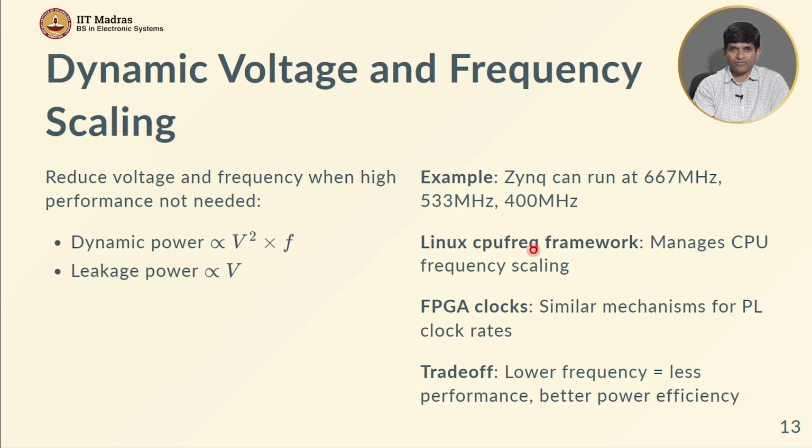You can do something similar for the FPGA clocks, because interestingly enough, in the Zynq systems, the FPGA fabric usually gets its clock from the PS, right, and it is possible using software to control the clock that is being fed into the programmable logic, right, which is good news. It means that you can basically control the clock being sent there through software.